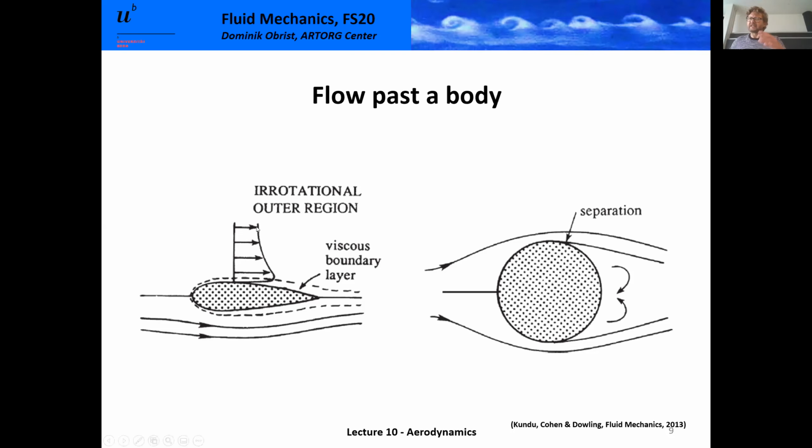And from these, we can also compute the local pressure forces. So if we look back at our blackboard, the pressures, the yellow pressures, are quite well predicted by the potential flow theory, and the red tangential shear stresses are quite well predicted by the boundary layer theory.